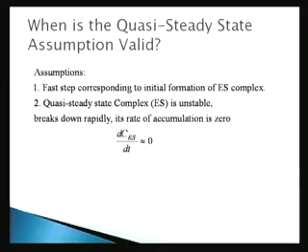you make that assumption. So that's always, when you validate a model, for example, if you have a lower dimensional model, you use an average model and you want to validate your average model, what is the procedure? You take the full 3-dimensional model, compute the solution of that, you take the average model, compute the solution of that, and compare the average solution with the full solution. If that error between the two is not high, there is obviously going to be an error, because once you make an assumption, there is always going to be an error. But if the error between these two is not very high, then you say that your assumption is more or less correct. So that is what we are going to do.